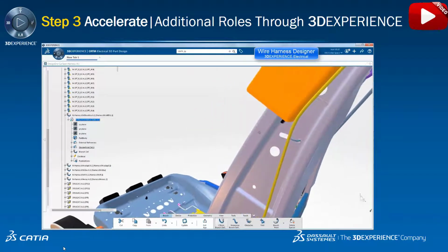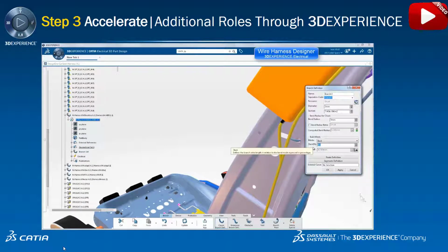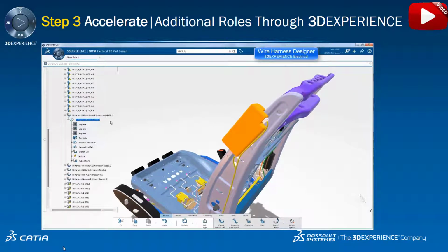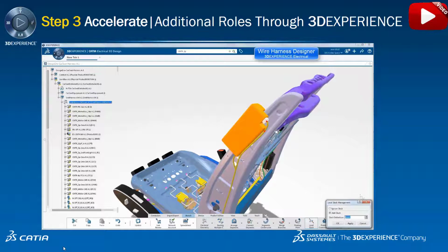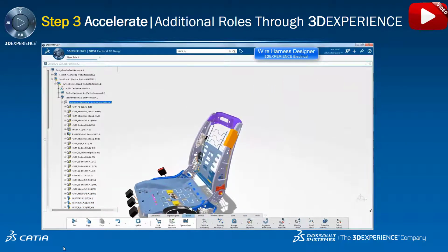We connect to the end of the connector we just placed, and we can add a branch point here from the bundle just created to another connector for the grounding of this airbag unit. We can give it a little bit of overlength to enable the easy connection or disconnection of the cable. And we're going to do the same at the top using local slack between the two red points. And they want an overlength of 2 millimeters to make it easier to disconnect the cable.